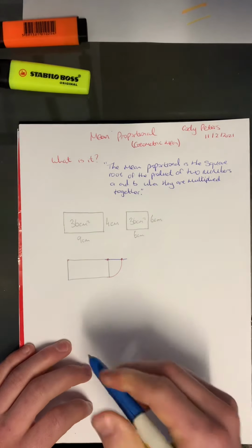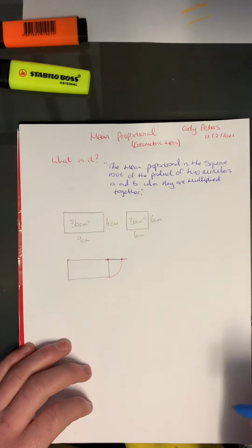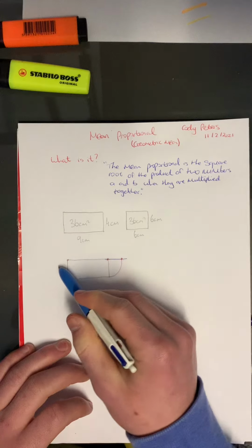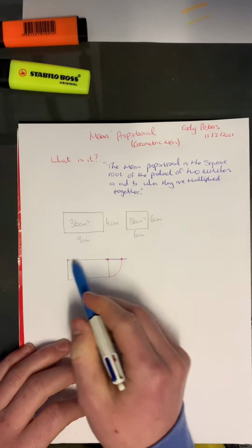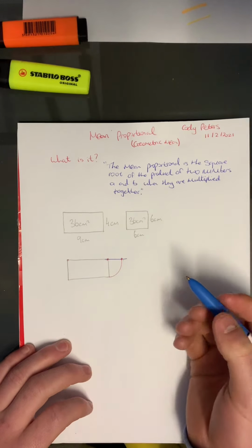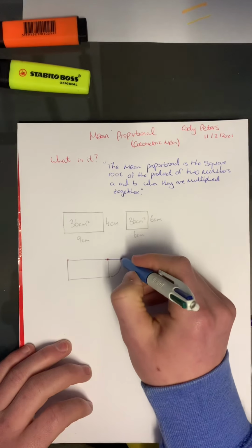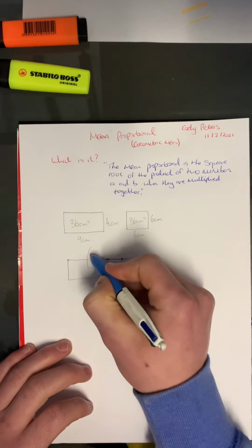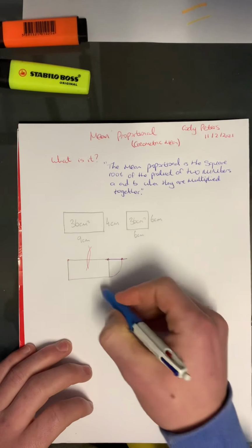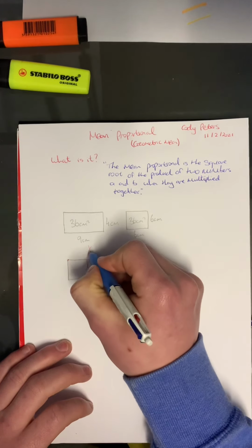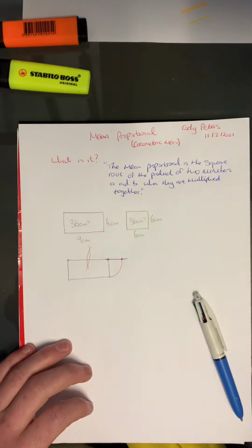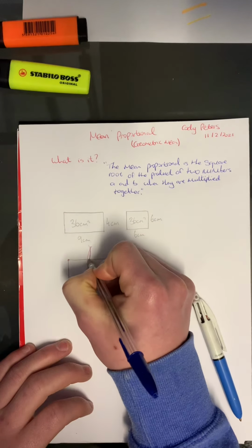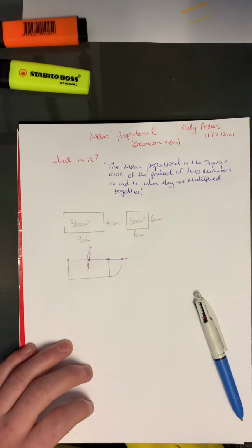So the next point in this process is going to be to find the center of this line. Essentially, we're going to bisect this line. By putting the pin of our compass here, striking an arc, and the pin of our compass here, striking an arc, we're going to find the center of this line. So here we found the center of the line.